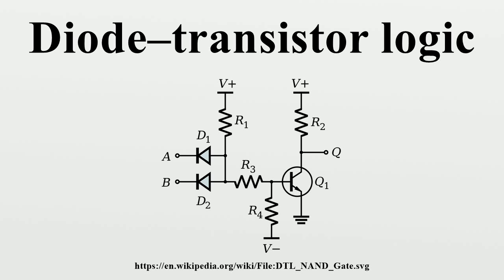Discrete. The IBM 1401 used DTL circuits similar to the simplified circuit; IBM called it complemented transistor diode logic. CTDL avoided the level shifting stage by alternating NPN and PNP-based gates operating on different power supply voltages. The 1401 used germanium transistors and diodes in its basic gates. The 1401 also added an inductor in series with R2. The physical packaging used the IBM Standard Modular System.